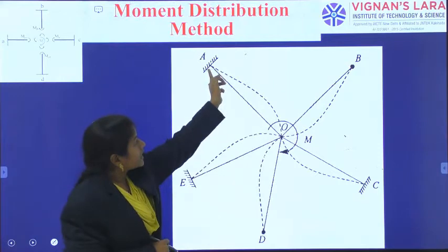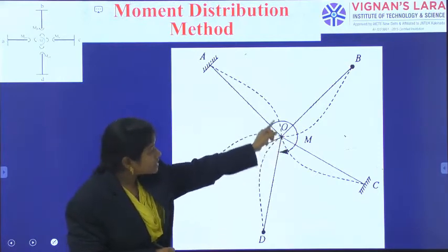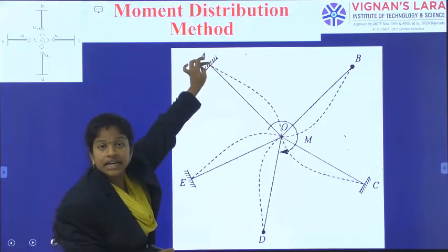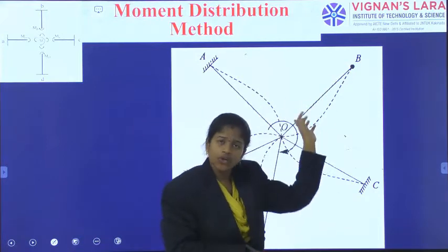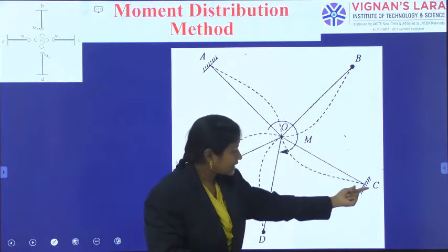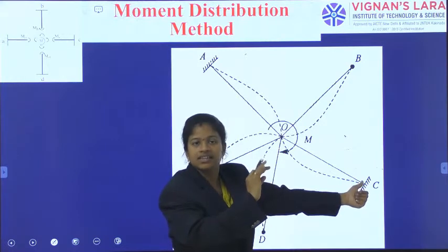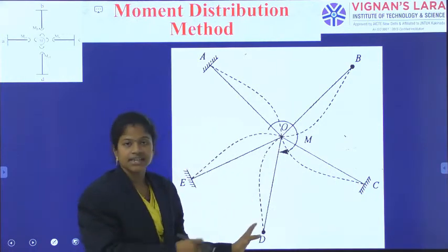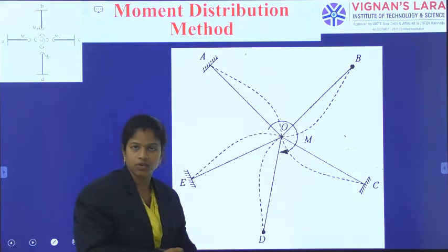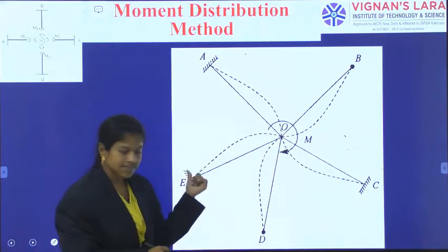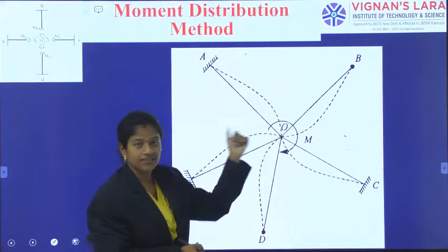See here, when it is fixed, you have observed some curved shape, but at the fixed end, zero slope. But for the hinge, you can give a smooth curve. Again, at the fixed, we should show some zero. Okay, at the fixed, there is no slope. Again, for the hinge, simply a smooth curve connecting those 2 points. Again, for the fixed, some zero indication and connecting the value.